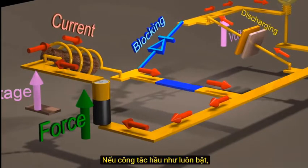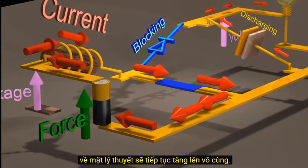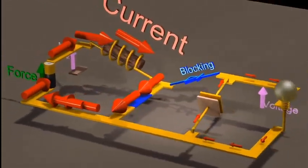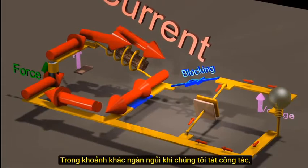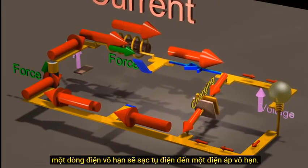If the switch is almost always on, then assuming we have ideal components, the current will theoretically keep increasing to infinity. During the brief moment when we turn the switch off, an infinite current would charge the capacitor to an infinite voltage.